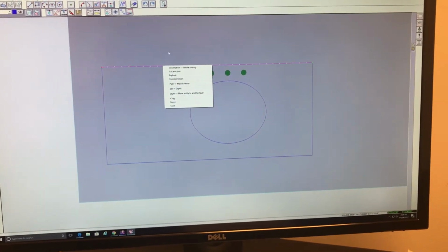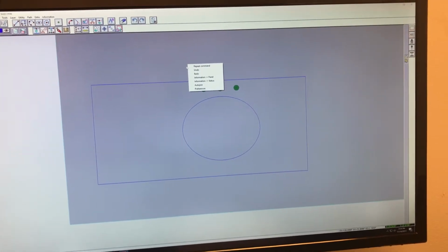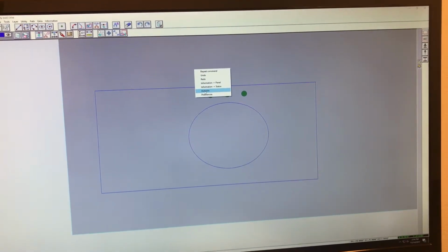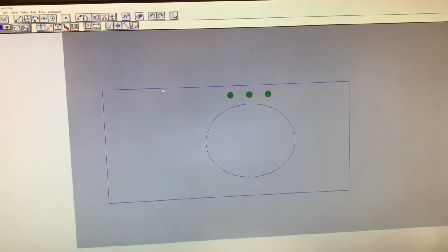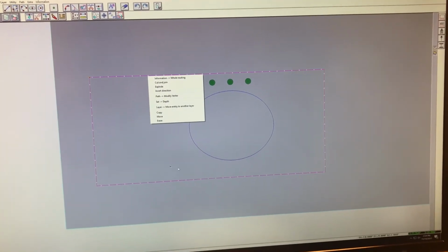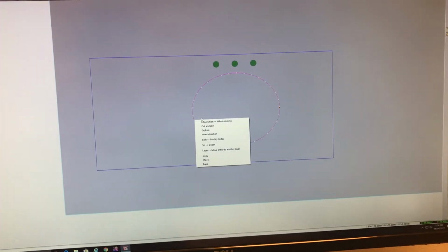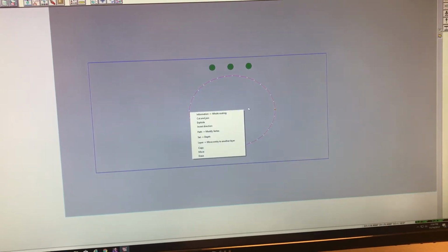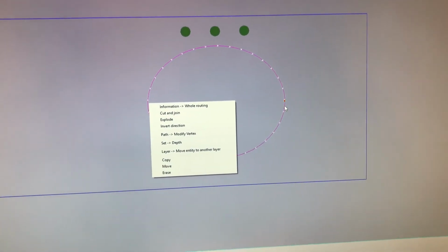We have to make sure that our piece is joined, which it's not. Right click anywhere not on a piece or part, auto join. Okay. Right click again to check everything. We're going the right direction. It's all joined. Check the vanity also. At this point, this vanity, if I right click here, you see this little dot right here. This is our start and finish point.